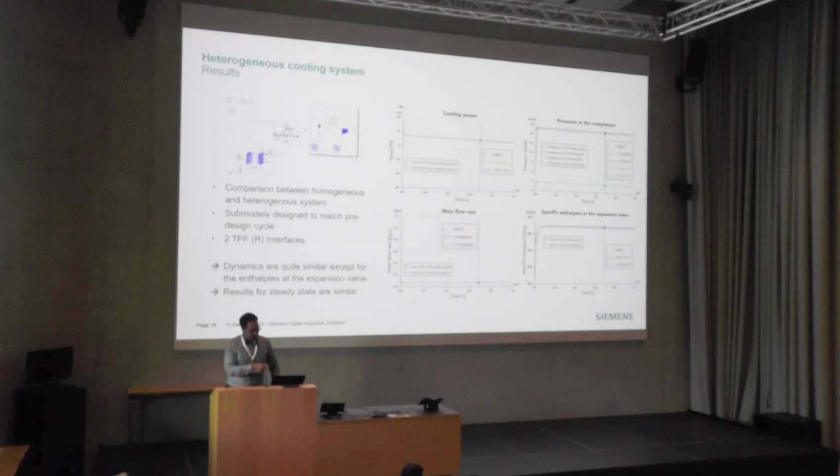And here we have the comparison between the homogeneous system, fully causal, fully from Simcenter Amesim, and the heterogeneous one created thanks to this AmeTpfMedia and the TPF interfaces. As you can see, we have quite similar results in the dynamics of the system, except for the expansion valve. And for the steady states, the results are very, very similar.